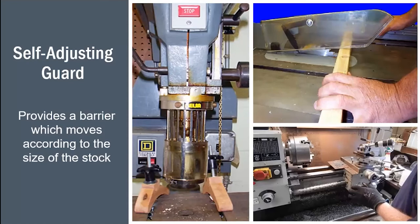Let's also note that they're missing a chuck guard on this lathe. But these are pretty reliable, less likely to see issues with adjustable guards or self-adjusting guards. But the things we do see is when they're just removed for whatever reason, or they get damaged. And sometimes it's damaged and then removed and not replaced.